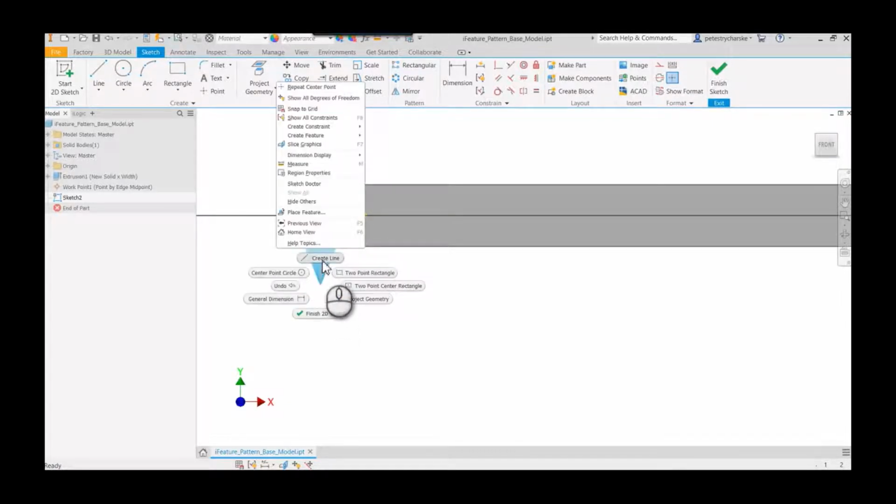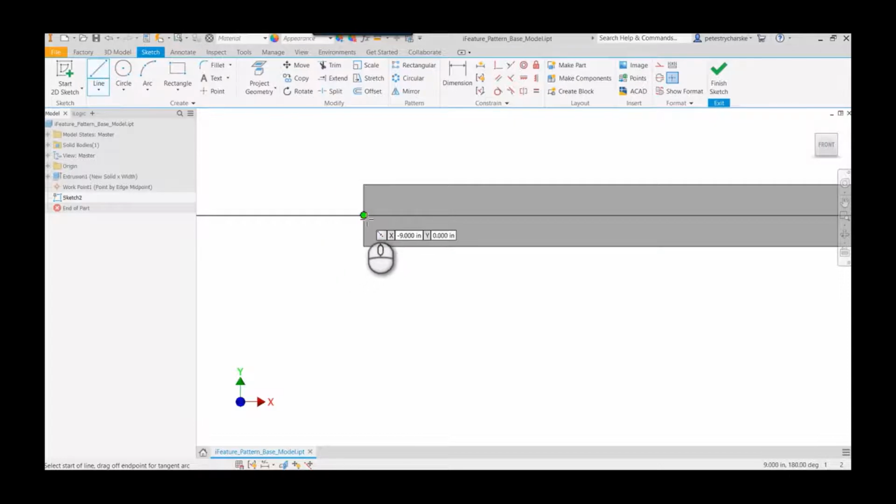And then from there, we are going to generate a line. This is going to be that end dist. You could hit delete here, look up the parameter. That would be the whole end dist. Cool. Hit the tab key, and now we draw that out straight across. So there is our location, and I could either stick a point on the end, or I can click on this point and make it a center point format, and there's going to be the location for the hole.